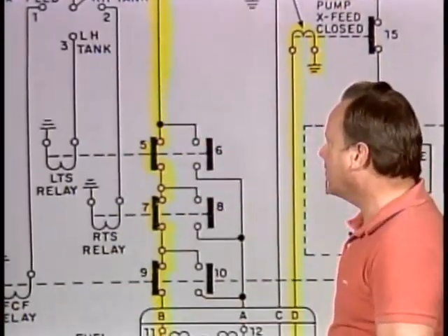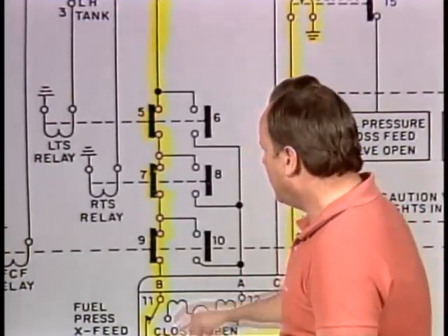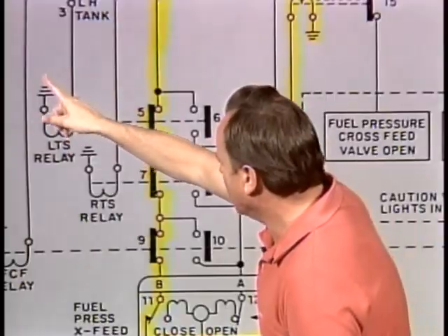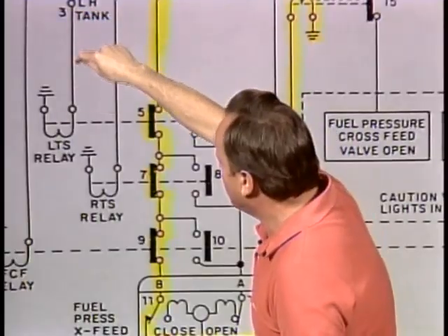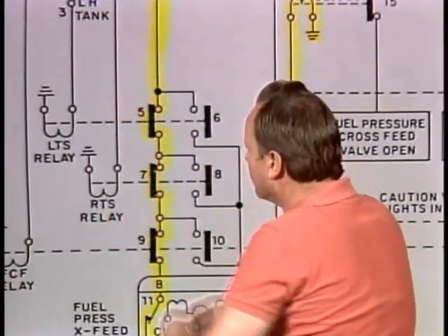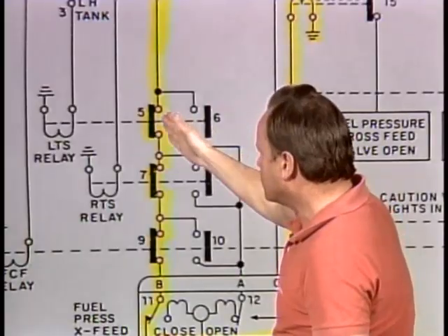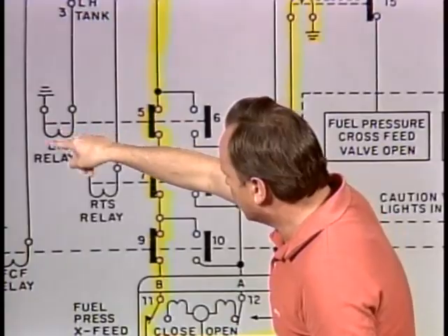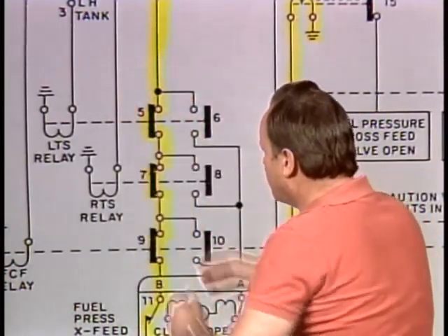Now, this is the concept of a relay, and let's take a look at it for just a second here. First of all, notice that we've got a ground right here. And what happens is, if there were power to this relay, this switch, this whole assembly would move over. A relay is an electromagnetically controlled switch. And if you put power on the electromagnet, which is what you have right here, an electromagnet, a coil of wire, then you're going to pull both of these switches over.